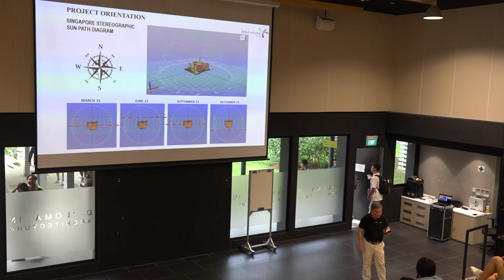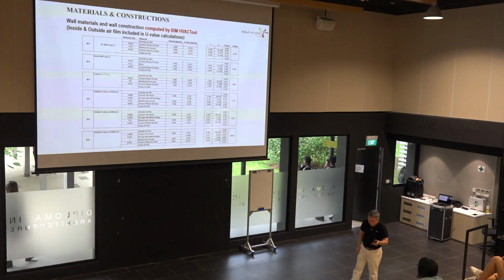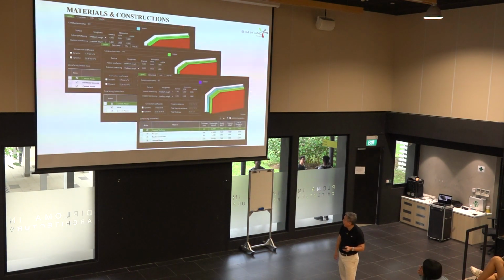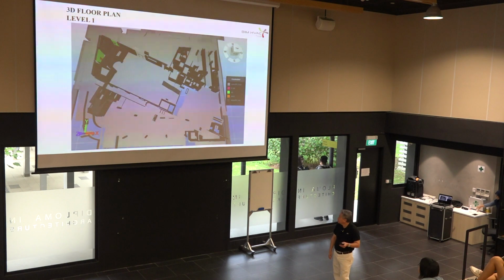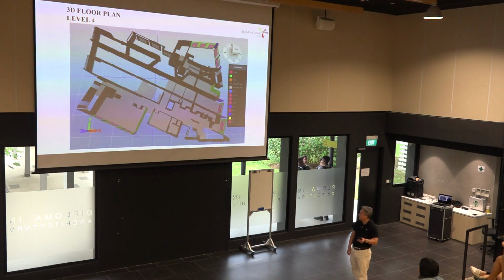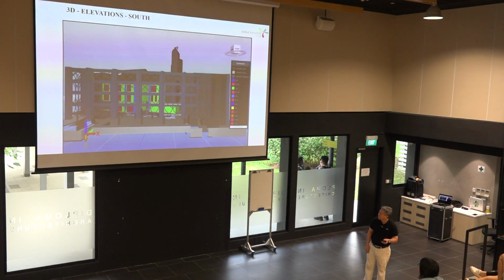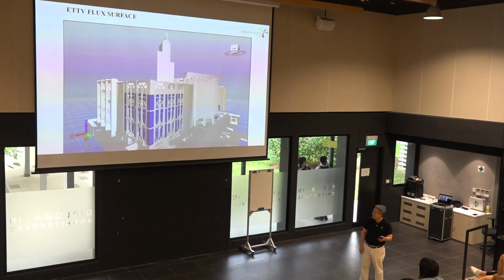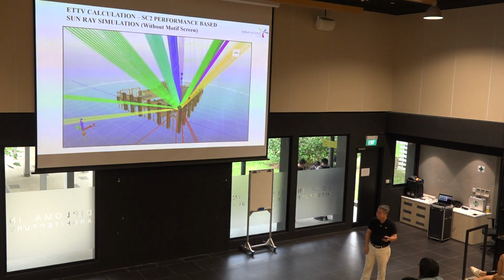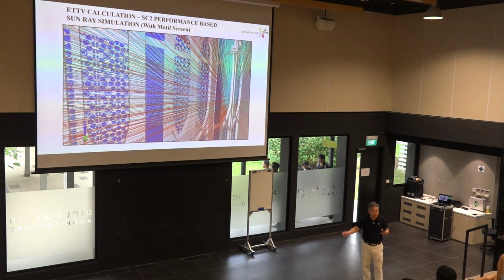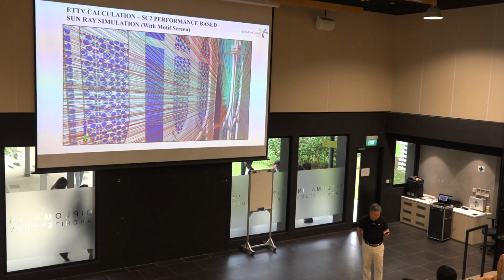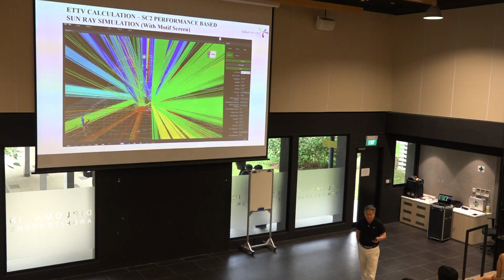So this is almost impossible to compute by hand. You need to have simulation tools because you need to do a ray tracing kind of activity to quantify the net shadow coefficient, because the perforated screen will cast a lot of shadow. It's just like the Changi Jewel project, right? There are a lot of shadows. So you need to do that.